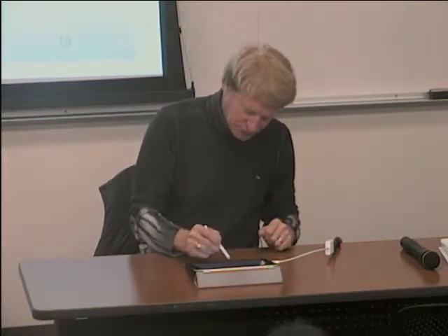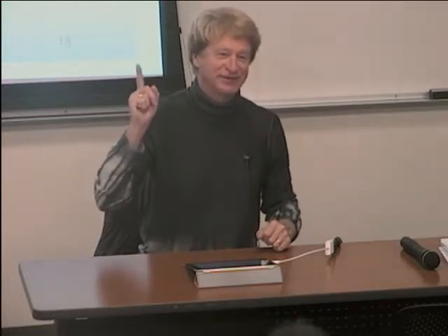So you have a large logical chain from the top to the bottom. Minimum, minimum, minimum, minimum, minimum. These are multiplexers, by the way. It's not hard. So all the way to the bottom. And on the side here, you're going to have a number of winners. Ultimately, the one that's going to be the winner is the one at the bottom that says, I was the last winner. You want to find that. That's the address you want to put out.